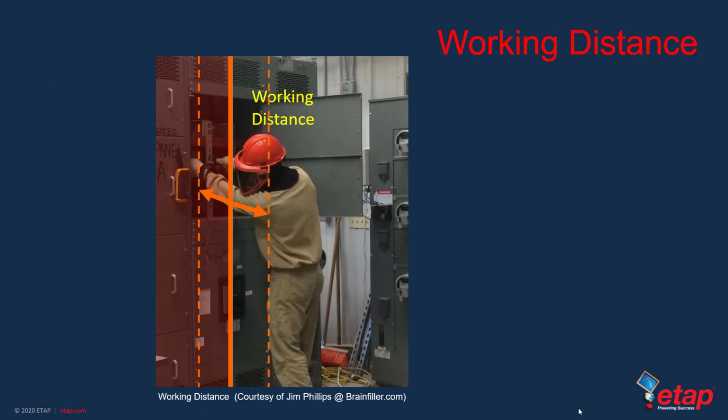Many times, arc flash studies are only done based on single working distances for each voltage class. Typically 18-inch or 24-inch in low voltage and 36-inch for medium voltage and high voltage. However, with the concept of C areas, the engineer in charge of performing the analysis can perhaps specify an expected variation on this working distance.